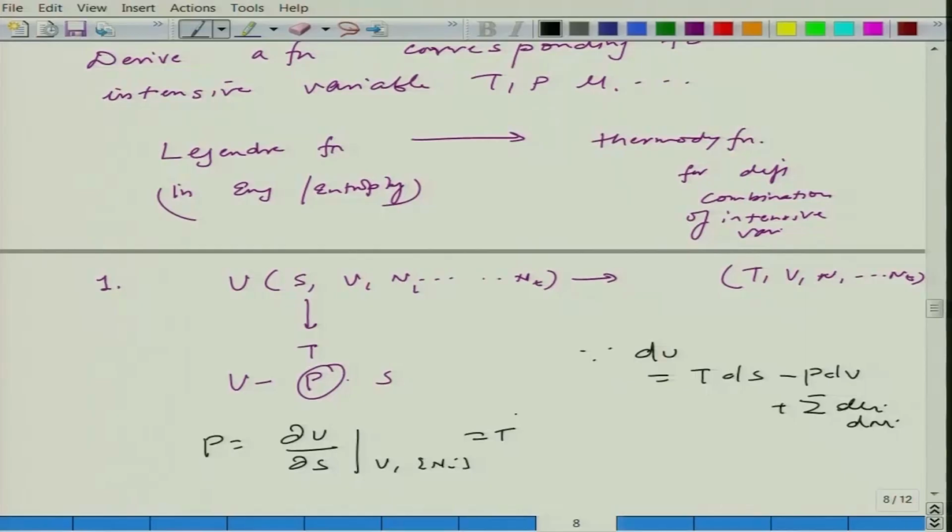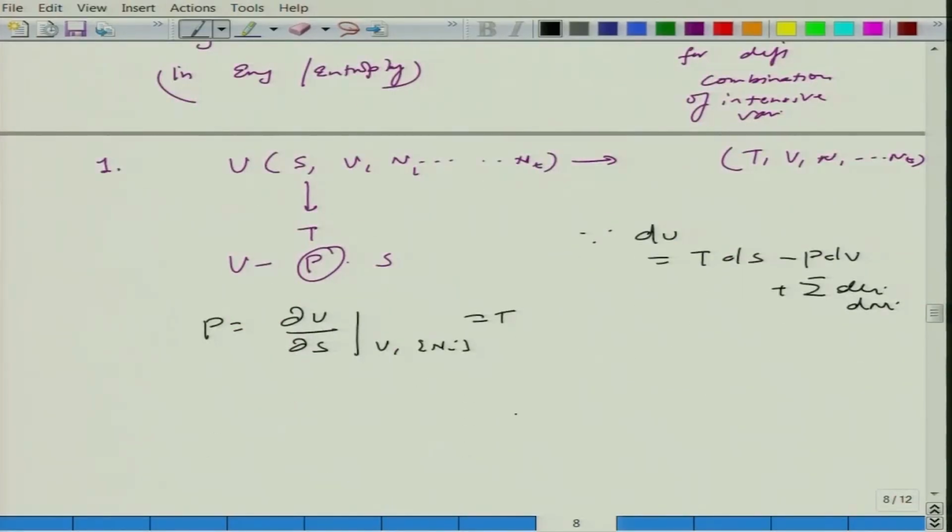Okay. So, what we have is now a thermodynamic Legendre transformation function, which is nothing but U minus TS, and this is what we define. So this is phi now; this is what we are defining in order to differentiate this from the different Legendre functions which we are going to get. So, this function we now call A. Okay. So this is nothing but the Helmholtz potential. Sometimes this is also called Helmholtz free energy. So this free energy concept will come a little later, but I am going to just write it down.